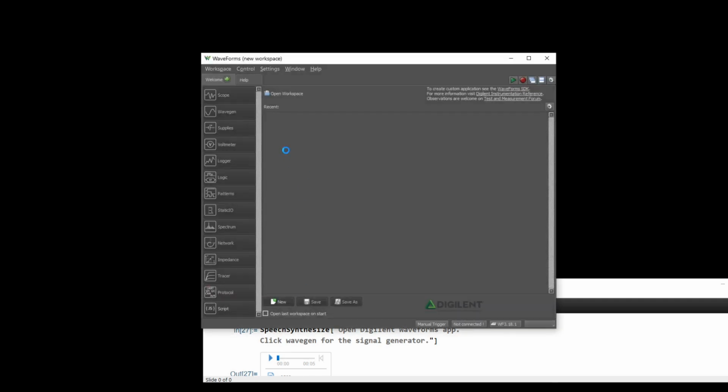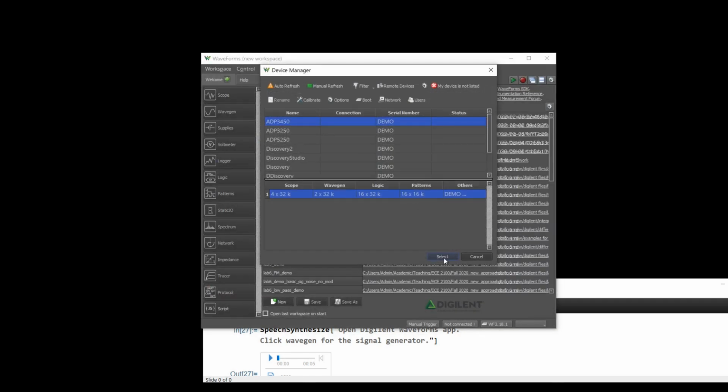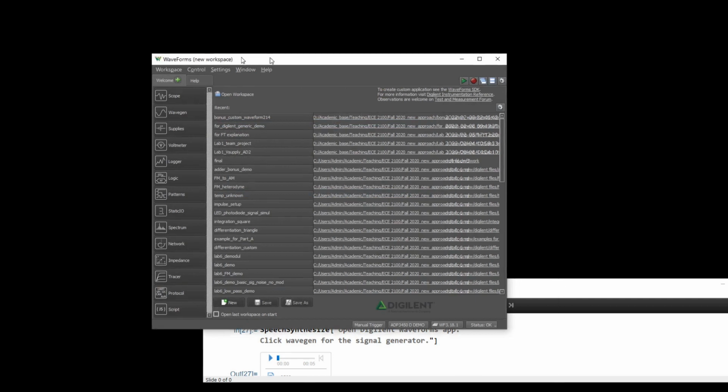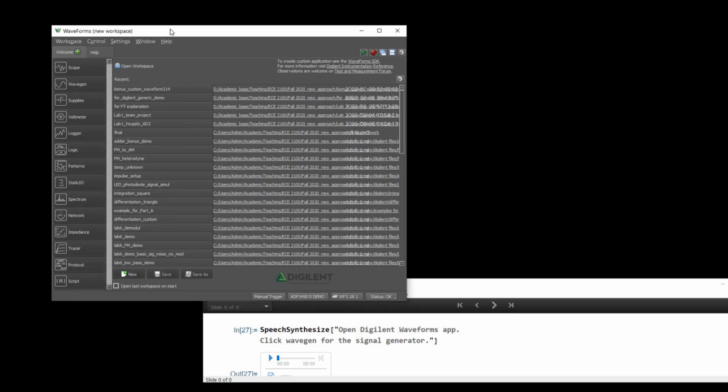It is strongly recommended, and will be required in Lab 5 and 6, that the experimenter uses options Basic and Custom in Digilent AD2 Wavegen output. Furthermore, it is required for the lab report that if a circuit input and output are to be demonstrated, it should be presented in a two-window side-by-side format. The following shows how these can be done.